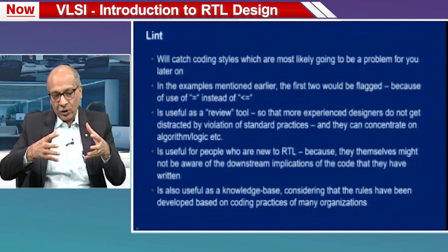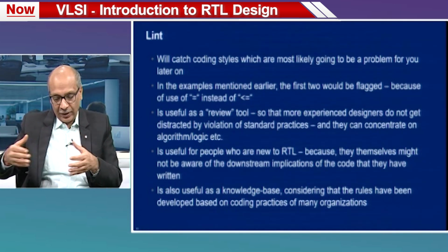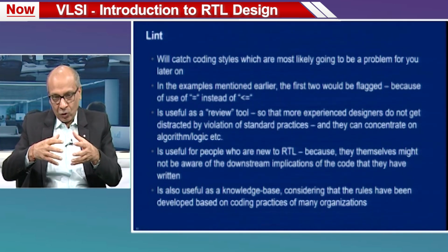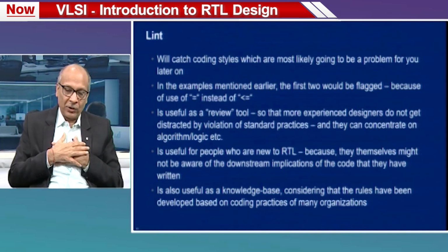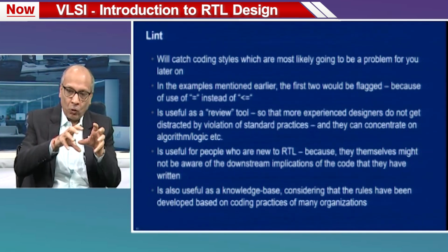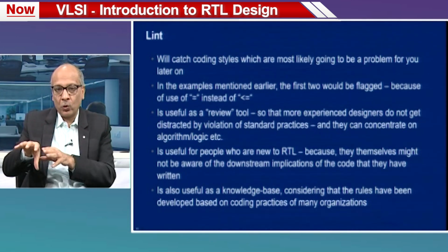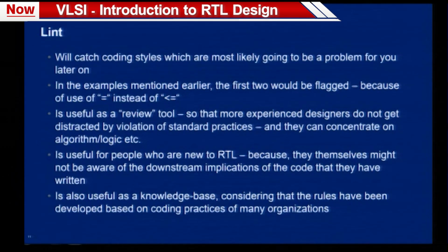And linter tools, I will see in the next slide probably, also grow based on design knowledge. I learn something based on a mistake, I can code that learning into a linter tool, so that any other designer in my company can make use of that learning. The linter tool will use that learning to check other people's code also.